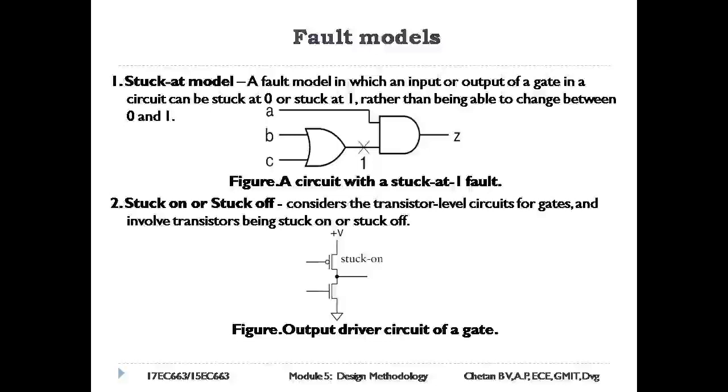Other models include bridging faults. Bridging faults represent short circuit connections between signal wires. Delay faults include the propagation delay of a circuit being longer than normal. Another type of fault is faults in storage elements.